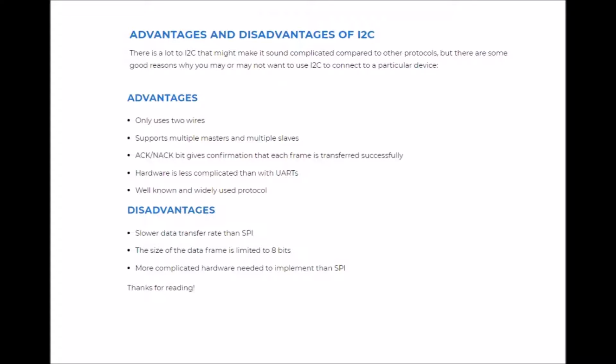It only uses 2 wires. It supports multiple masters and multiple slaves. ACK/NACK bit gives confirmation that each frame is transferred successfully. Hardware is less complicated than with UART. Well-known and widely used protocol.